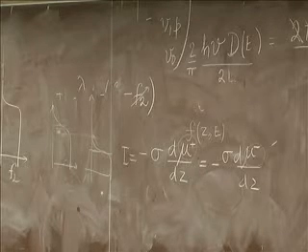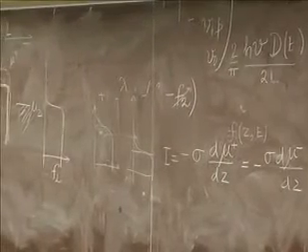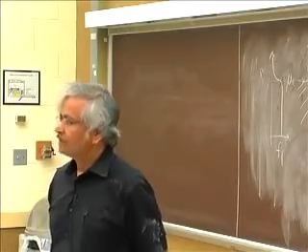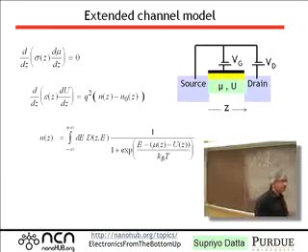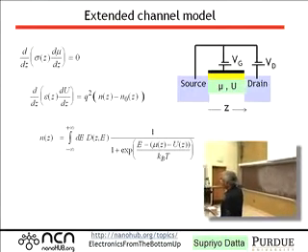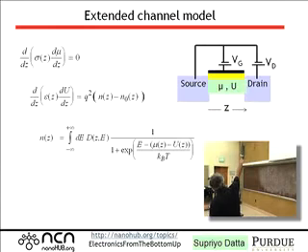So the question I had was, why does mu not depend on mu plus and mu minus, not depend on a channel potential? The way I usually think about it is that in these devices in general, you'd have one equation which I've written on top. That is what you might call a transport equation. Where did that come from? What is inside is the current, that's the sigma d mu dz, as I was saying. Current must be the same everywhere, so di dz is 0. That's the top equation.